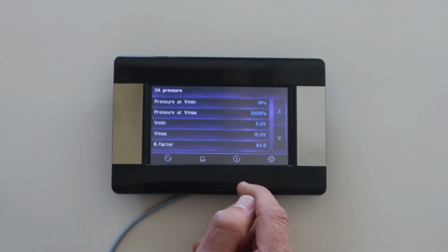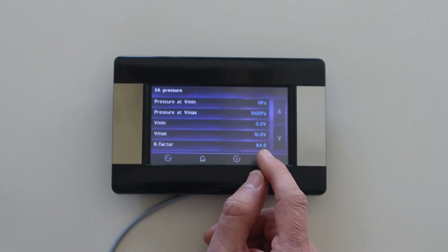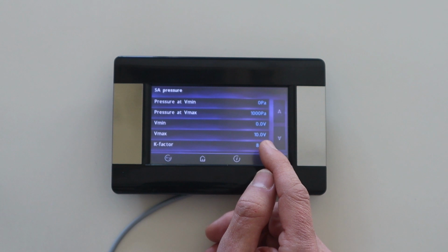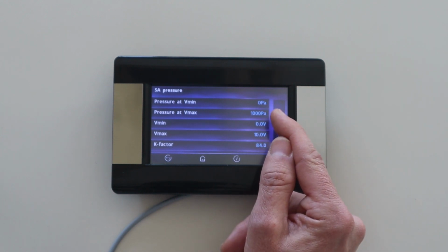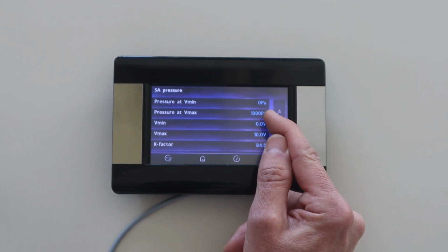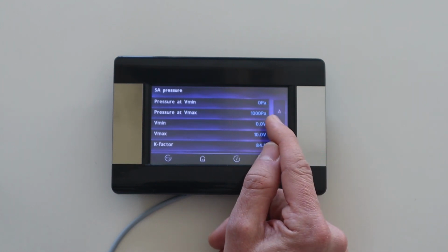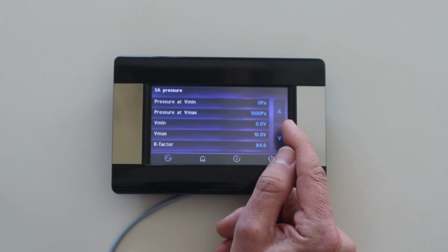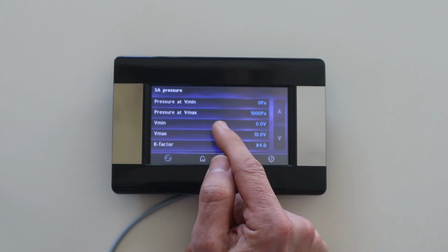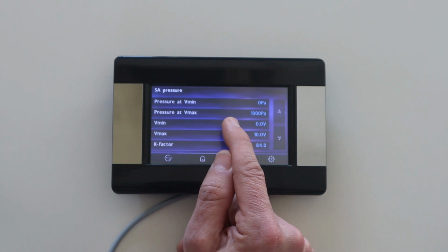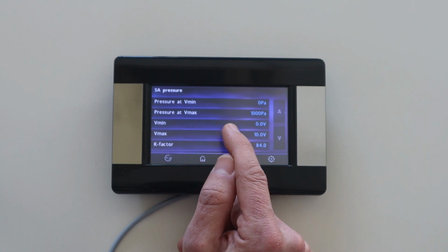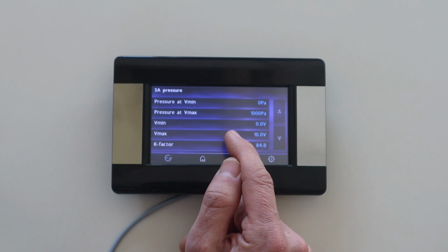In the case of our TTPs, the pressure transmitter itself allows modifying the settings, and it's possible to load different pressure ranges in the TTP. So the only important thing is to set the same pressure range here as in the pressure transmitter. If we know the value of the pressure to be maintained, it's good to select a range that should be about double the pressure maintained.